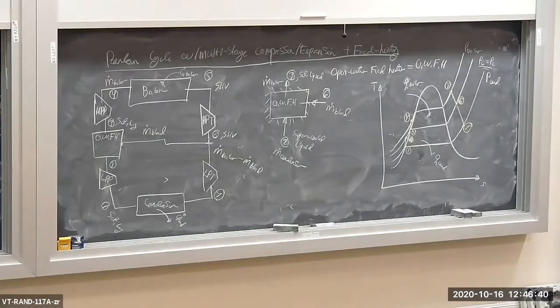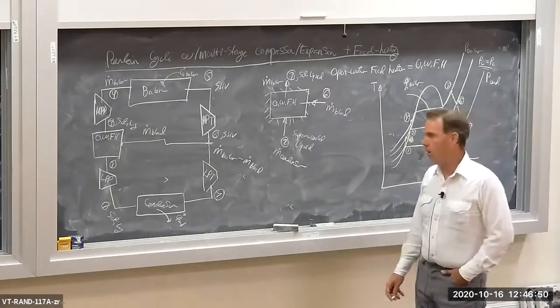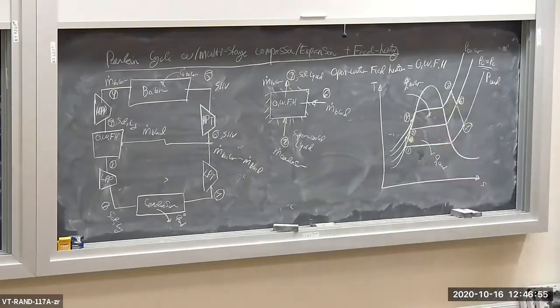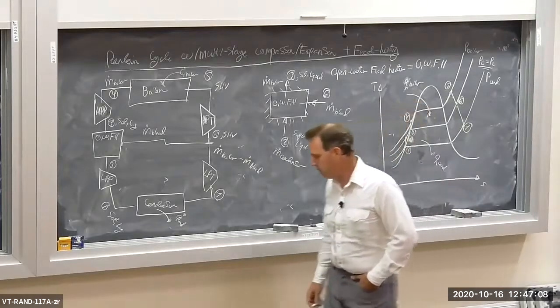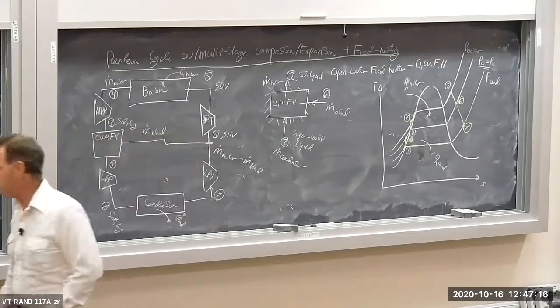So power plants, and, well, power plants on ships as well. So propulsion plants on ships, which often are operating off of a Rankine cycle, especially the old ships that were oil and coal fired, those have various open water feed heating systems as well, okay? So this open water feed heating gets you an extra % or 2 in efficiency of a Rankine cycle. Not as amazing an improvement as with regeneration in the Brayton cycle that we looked at last time, okay?